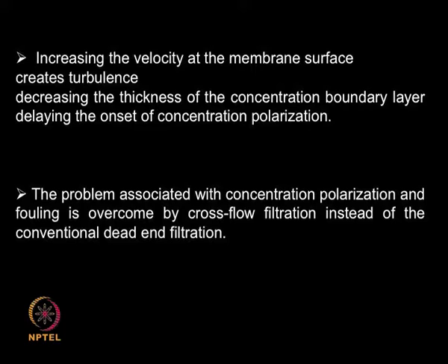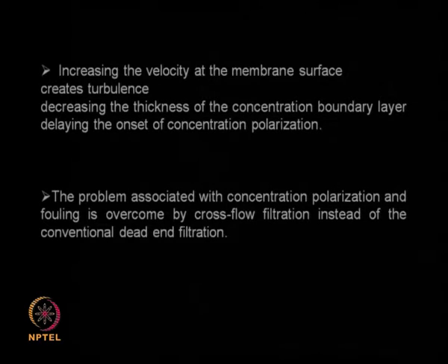So far what we saw is a perpendicular flow, that means the flow is perpendicular to the membrane surface, or the membrane surface is perpendicular to the flow direction, okay, or that it is also called dead end filtration. So normal filtration is also called dead end or perpendicular filtration.